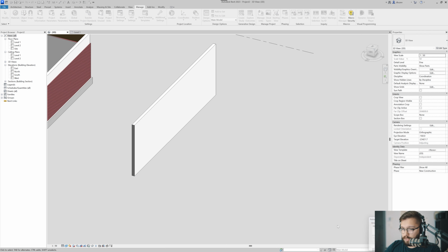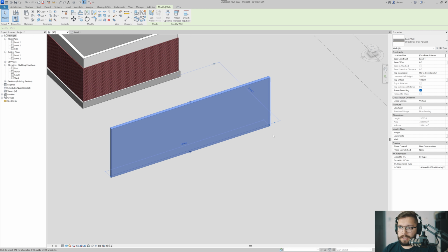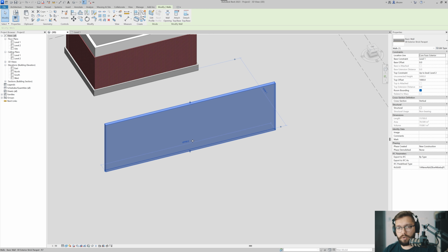And actually by doing this, you revert the wall back to its original state. And let's do the power move where we're going to dissect this wall using not just lines, but reference planes. This is where the power move is because it actually gives you greater control outside of the wall. So you'll be able to change things like reference planes and grid lines, which in turn are going to be manipulating the wall. So you don't have to go into it every single time, okay?